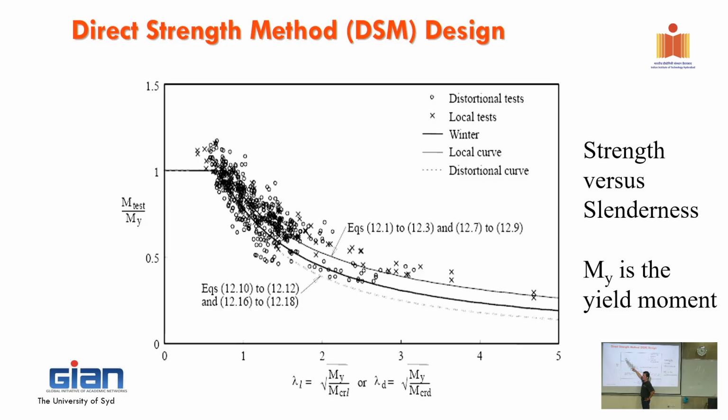So there is variation in here. Of course, that's why we have to run the probability analysis, and we get a resistance factor, phi factor, coming in, okay? Or reliability, what is that? You know beta, right? The safety index, so we have to achieve the target 2.5 beta to calculate the reliability.